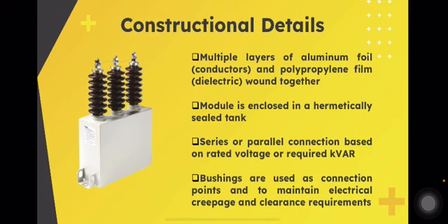So, why are the power capacitors required? In a distribution system, these power capacitors provide reactive power to offset inductive loading from devices like motors, arc furnaces, and lighting loads. The incorporation of power capacitors into a power distribution system offers economical and operational benefits, including increasing system load capacity, reducing losses, and improving power factor.